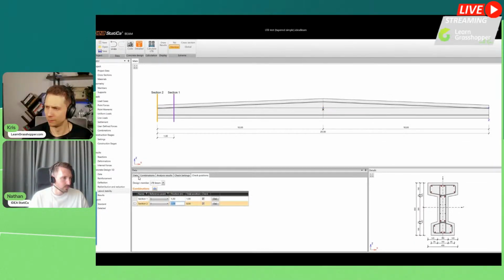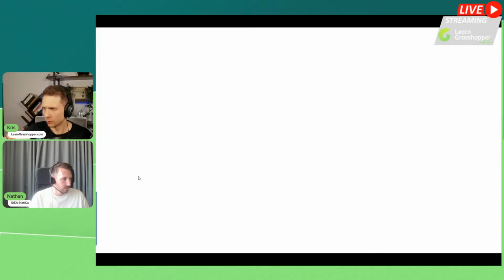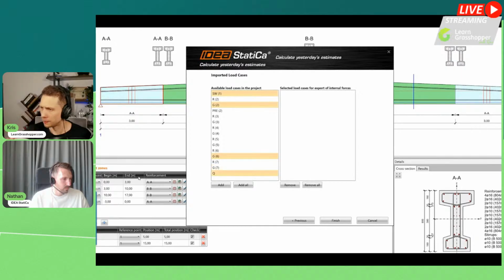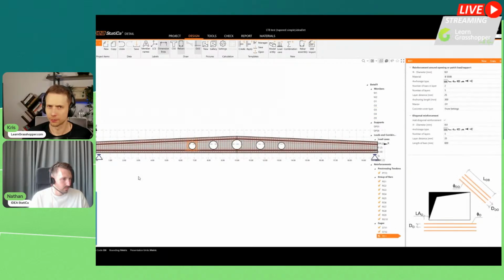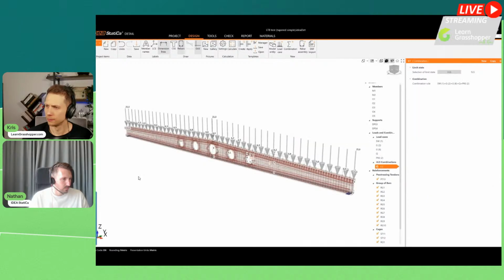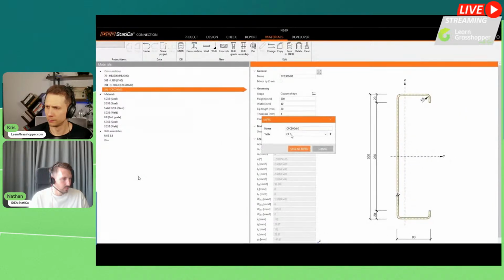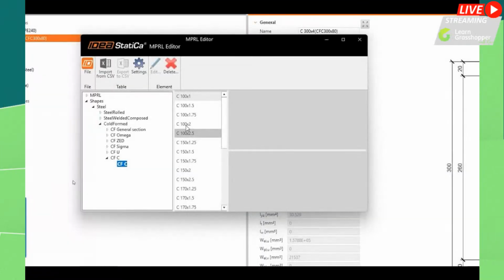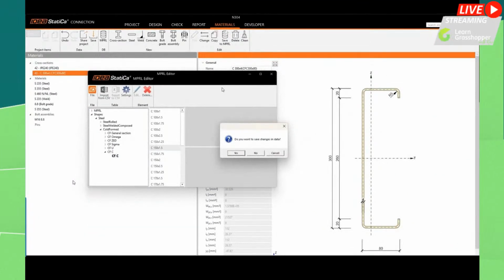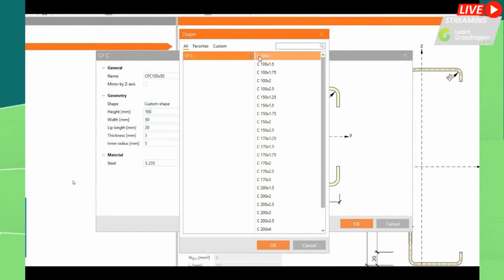All precast checks are now available, including lateral torsional buckling with construction stage effects. And if your members have openings, you can export tendons and reinforcement from beam to detail and run full checks without remodeling. No more repeating manual inputs. Custom shapes now work like standard library sections. Just create your own cross-section geometry, save it to the project database, and reuse it across any Idea Statica steel application.